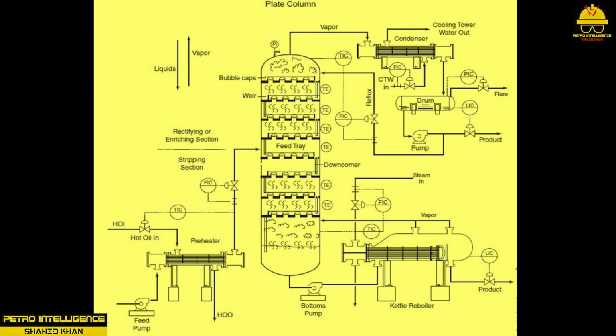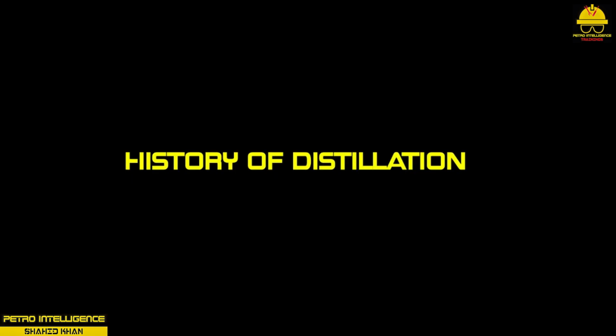A reboiler maintains the energy balance on the distillation column. Reboilers take suction off the bottom of the tower. The liquid in the tower is circulated through the reboiler. Vaporization occurs in the reboiler and these vapors rise up through the tower. Boil-up rate is defined as the balance of the product's vapor and liquid returned to the column from the kettle reboiler.